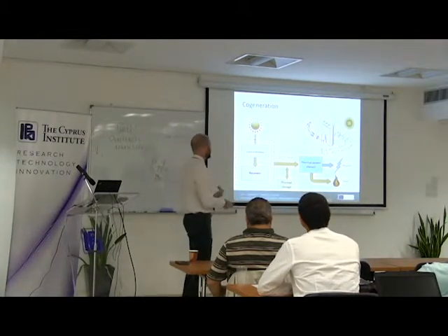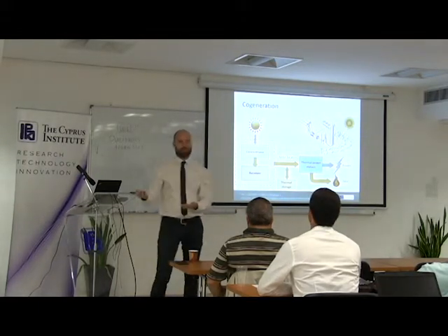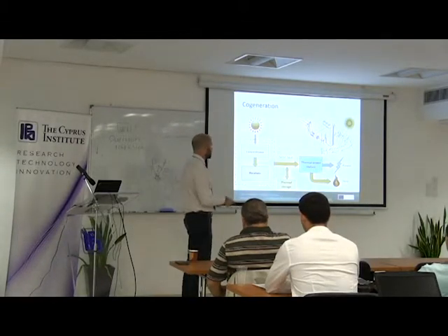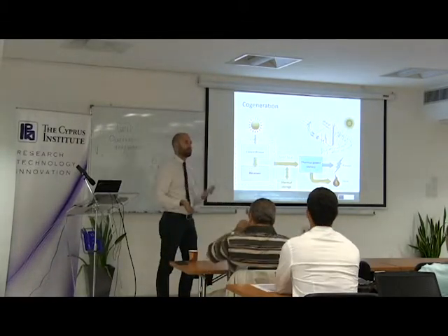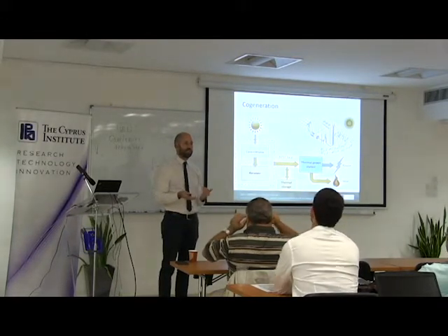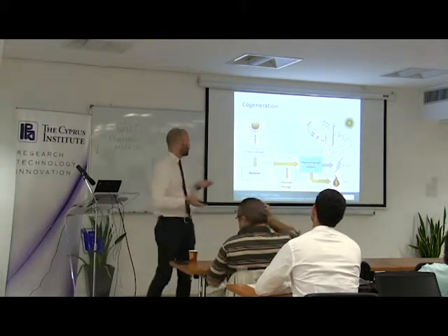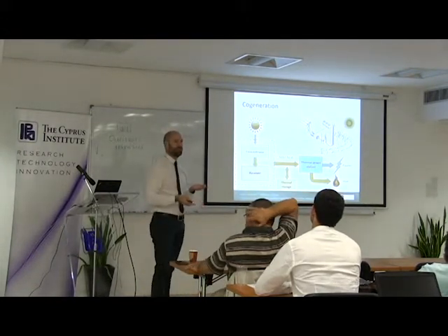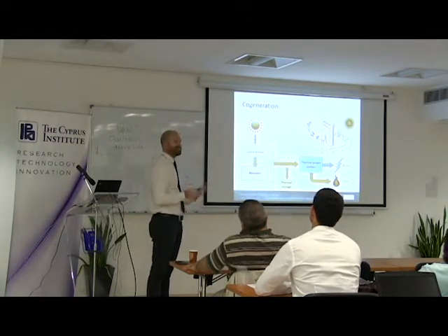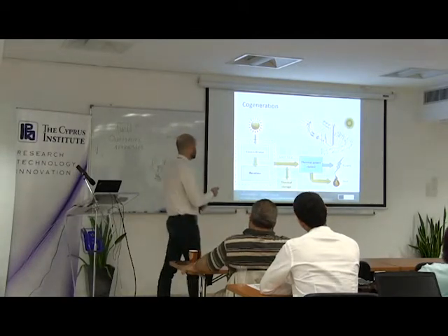On the other hand, if you lower the quality of this heat, you won't be able to use it, so you will be just rejecting it to the environment. Sometimes, like in the case of desalination, you can find a trade-off. So you can lower a little bit the efficiency of the power plant by increasing the temperature of steam condensation, and use this heat for some applications like desalination.